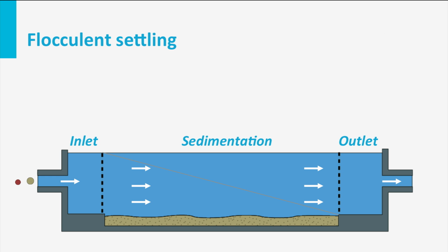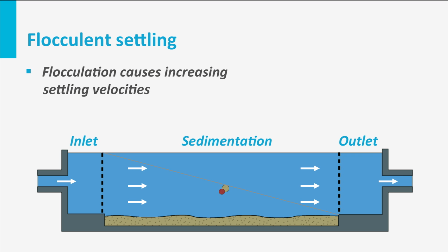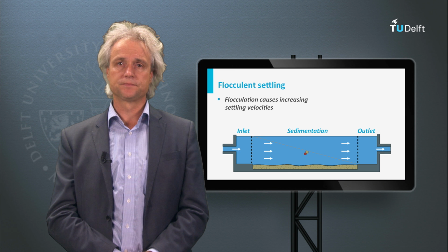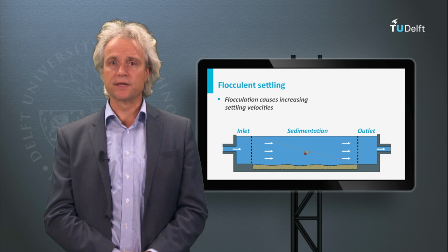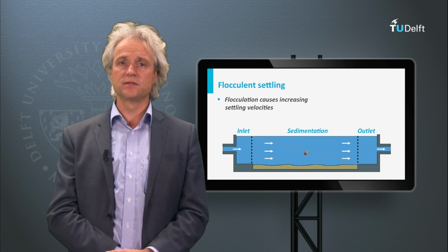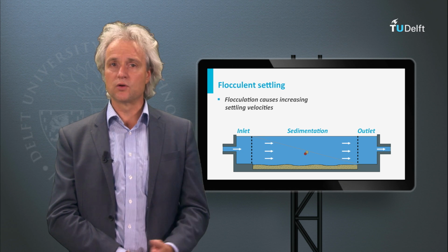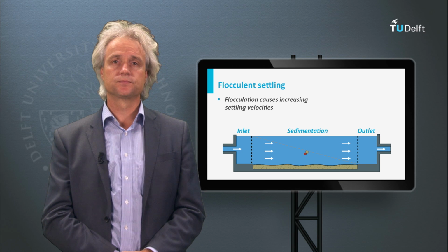The other type of settling is flocculent settling. During flocculent settling, particles agglomerate or coalesce or flocculate and have no constant characteristics. The particles vary in size and increase in mass, resulting in increased velocities during settling. Flocculent settling generally occurs with organic suspended solids, which are largely present in the domestic sewage and in our sewage treatment reactor.